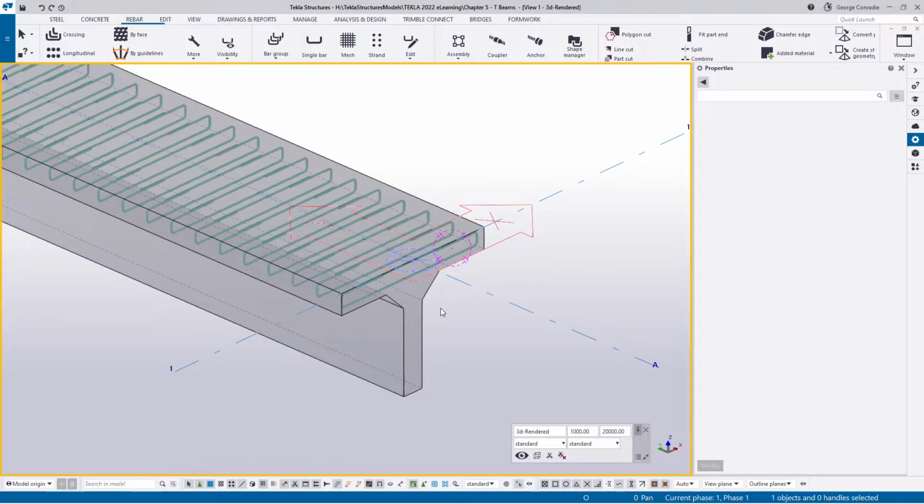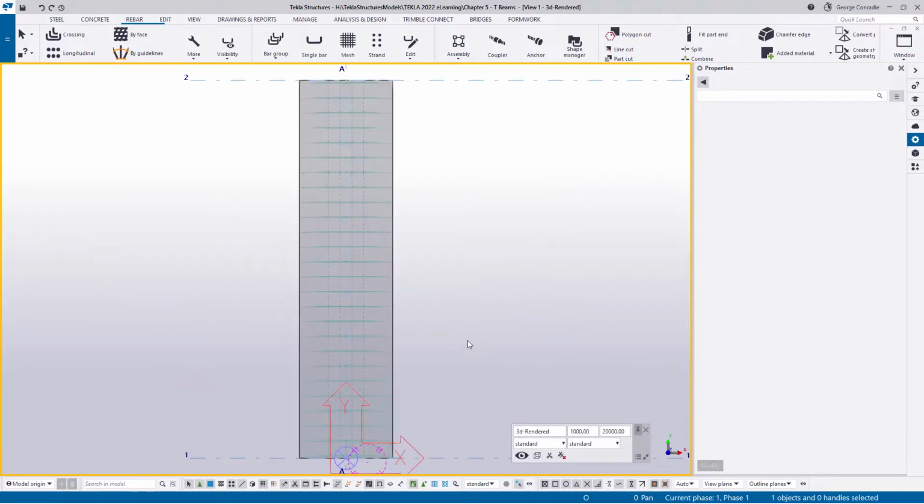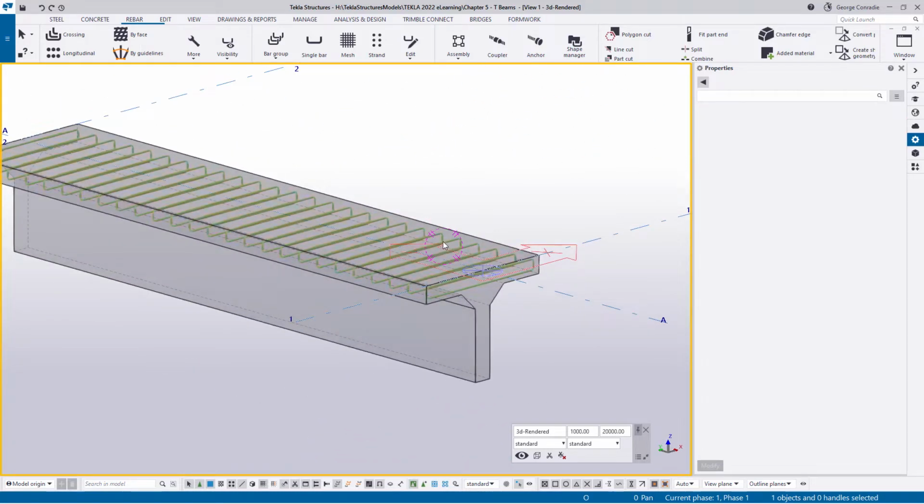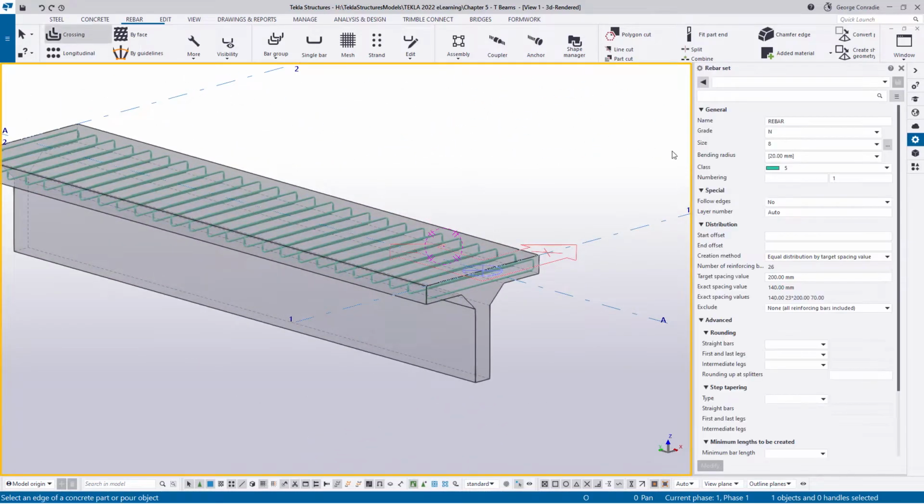So the next step we want to do is deal with the bars in the web, the outer layer, and so for that, I'll go into a 3D mode with Control P. I think this is the best view to do it in. I will this time go to a crossing bar. It's the same size, but instead of using a 5, I'm going to use a class 2 for the red, and I'll use the same parameters, and I'll hover over the web and just accept it.